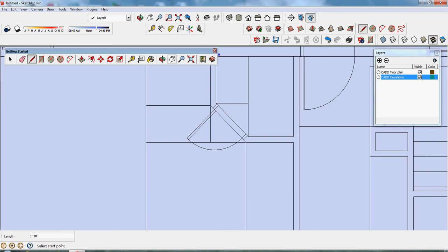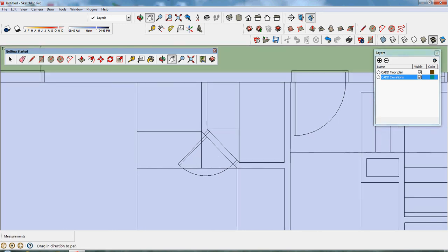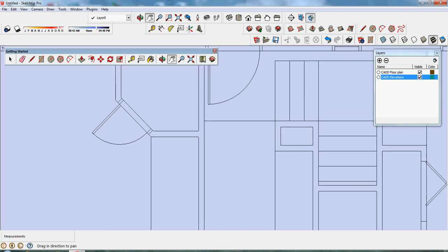Now at this point, we're going to go around and use the eraser. The eraser is going to erase these unnecessary lines because the plate has to come up as one uniform motion. And the walls that touch the outside walls also have to be erased so that they come up at the same time. You can see I've got some line work here. Oops, just do an undo there. Okay, and move along.